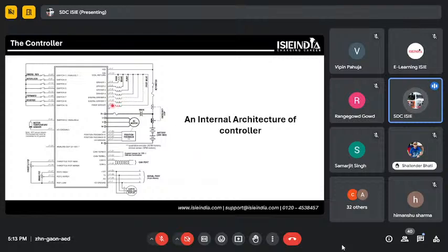Okay, so you can find that these are the three wires U, V, W, which are connected to the AC motors or any PMSM motor, along with the resolver and Hall effect sensor response wire connections, and B positive and B negative, the battery power source which we are giving to run the motor, right?